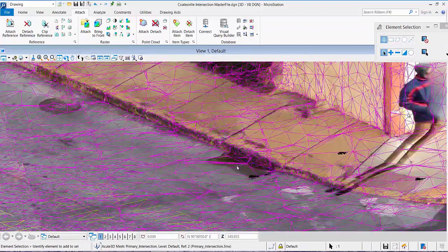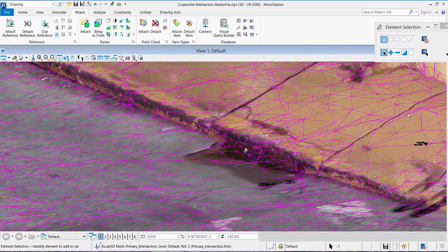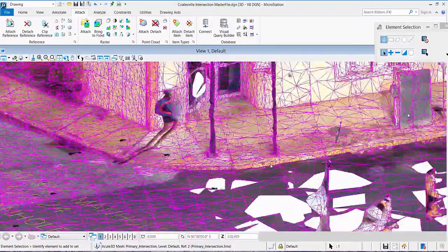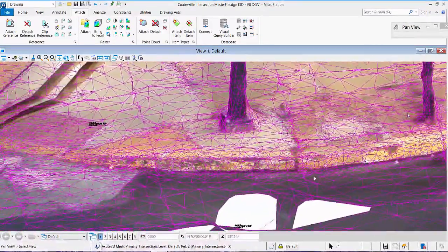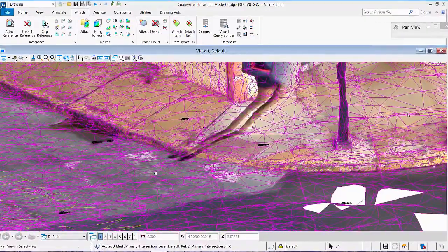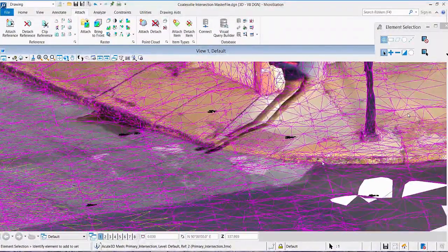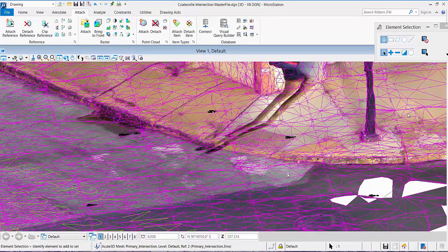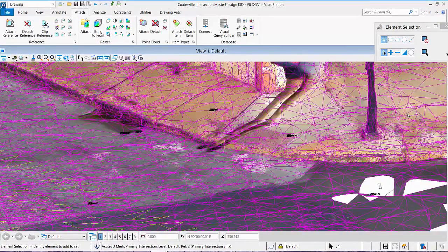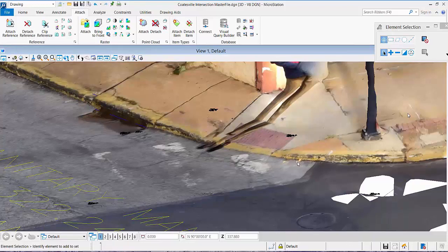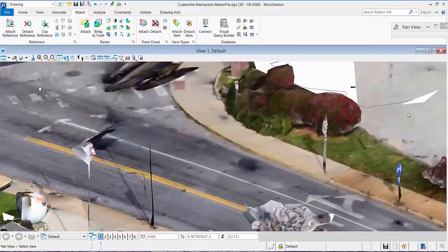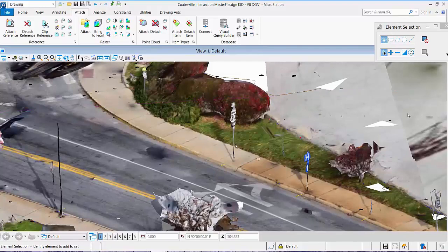And if I select it, we can see our mesh. From the mesh, we can begin looking around and analyzing the accuracy of our survey points. And actually what we would find is that our mesh is quite a bit more accurate than our survey points completed with a standard total station. The primary reason for this is the algorithm used within the survey doesn't allow for the correct bending of the lines. We can also zoom and look around and find that the surveyor missed various shrubbery and even a sign in a couple of locations.